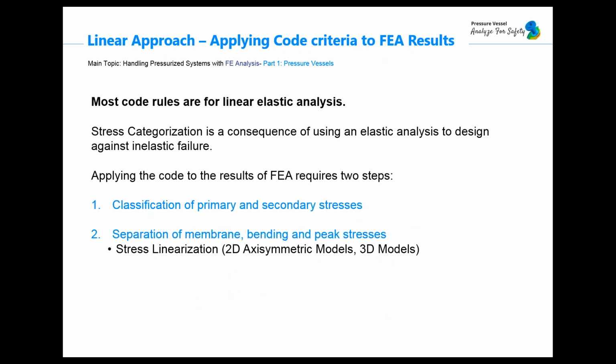But for FEA, the situation is not so easy in terms of classification for the stress limits, and depending on the element type, any kind of finite element software provides different result data. For a two-dimensional element, which is recognized as shell or plate depending on the code, results such as membrane and bending stresses are obtained directly and they are compatible with the code requirements.